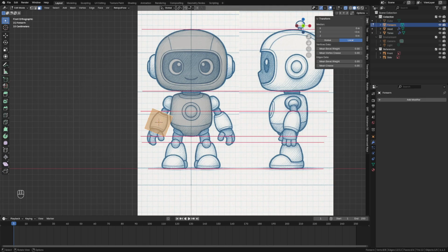faces to stay parallel. If we add a mirror modifier, you can see things don't work as expected because by default the mirror modifier uses the origin point as the symmetry center. We can fix this by choosing a mirror object, which uses its origin as the center for the mirroring.